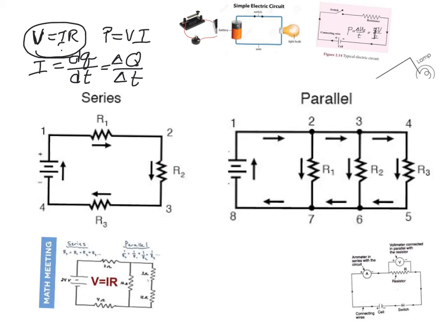And if this were 5, 6, and 7, that would be 11, 18 ohms. And if this were a 6-volt battery, you would take 6 volts divided by 18, and it means you would have 1/3 of an amp going through each of these resistors. And once we know that 1/3 of an amp is going through each resistor, we can then find the voltage.